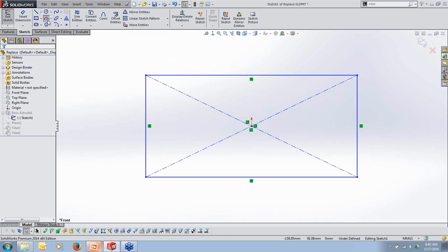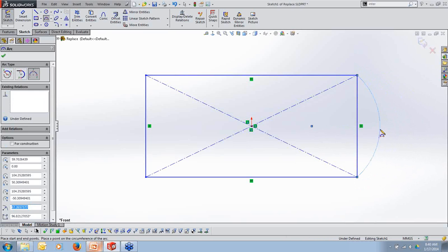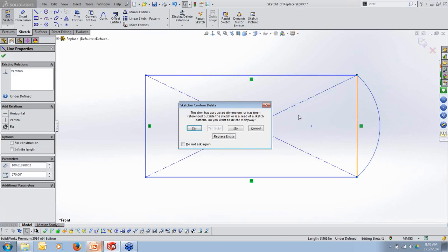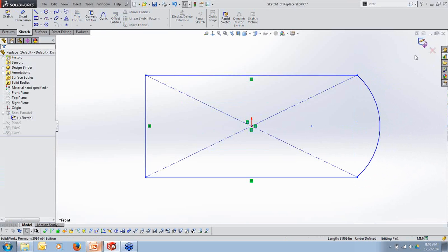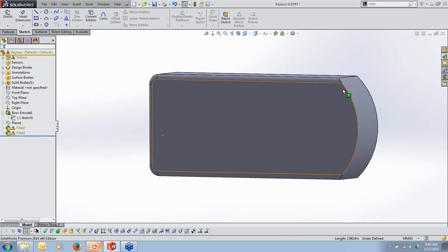If I go to swap this out with something else, so I just place some other type of geometry in here, and I remove this line, what happens is it blows up because that line is now not known by SolidWorks. It's just another entity that showed up out of the blue, and it has no idea how to remap that to where we're supposed to go.